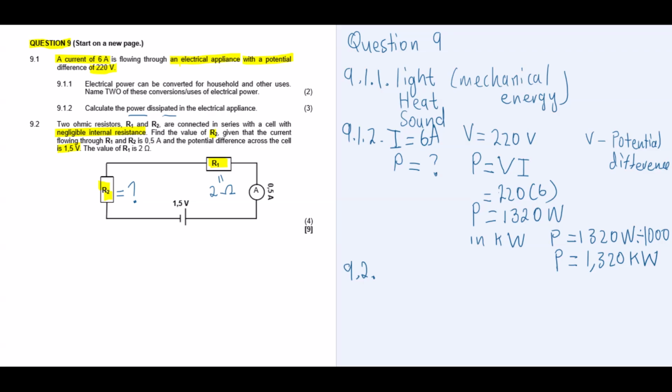We have to check the quantities, the information that we have here, for us to be able to calculate this resistance, right? So we know the total current is there. We know the voltage, it's 1.5 volts. It's only one cell, that is 1.5. So we don't have to multiply by 2 like the previous question, because this is already one cell and it's given 1.5, right? So this is the total voltage. And then what is the total current in this situation? The total current is going to be 0.5 amps, right? So I think we can calculate the total resistance